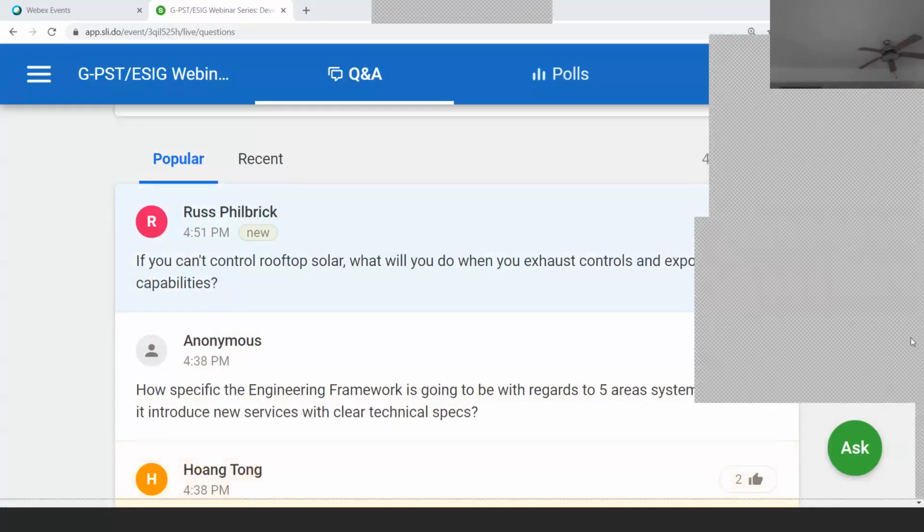Well, this is where it becomes quite a challenge. The interconnects between states facilitate the transfer of power, but only to a particular limit based on the security of transfers. So operational demand, which is already predicted to reach zero, so this is the demand seen from the transmission system, by, say, the mid-20s in South Australia. If that were the case, you obviously will need to start curtailing your transmission level generation according to what you can export. So you're still in a lot of wind, still in a lot of solar, and you also need